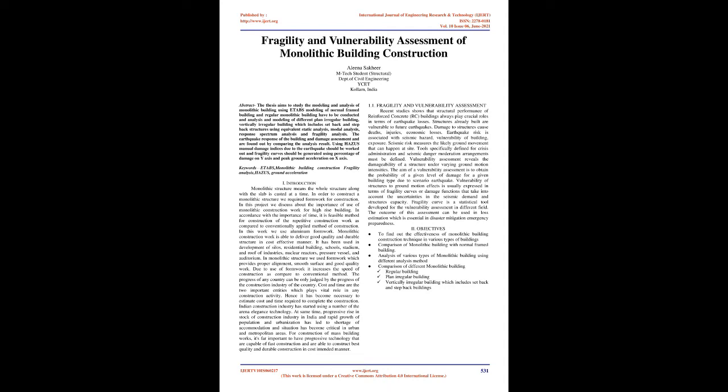The thesis aims to study the modeling and analysis of monolithic building using ETABS. Modeling of normal framed building and regular monolithic building have to be conducted, and analysis and modeling of different plan irregular building and vertically irregular building, which includes setback and step-back structures, using equivalent static analysis, modal analysis, response spectrum analysis and fragility analysis. The earthquake response of the building and damage assessment are found out by comparing the analysis results.